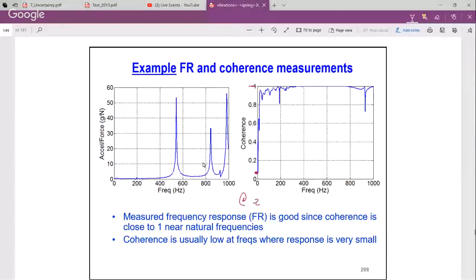All right. Now, the only area that really matters for our purposes is where we extract the modal information and the vibration model information. We're really only interested in where the system responds. Those are the points of interest for us, not really points, but ranges. We see we're able to get a peak from, say, 450 to 550, and then 950 to 1,000. Those are the ranges of frequencies where we're going to be extracting data. So those areas are important.